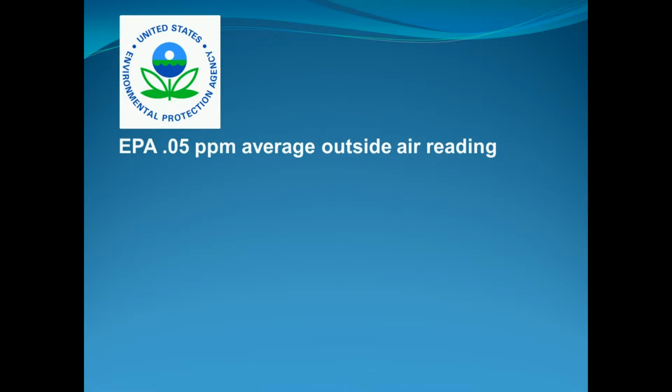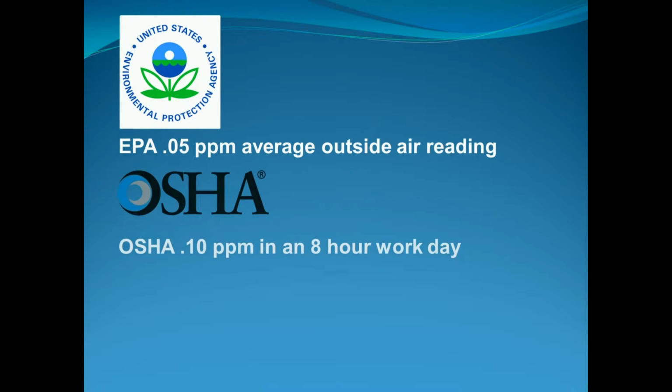So ozone is Mother Nature's way of oxidizing gases, but it's done in a specific amount outdoors. Outdoors has about 0.05 parts per million of ozone. Indoors, OSHA is a pretty strict organization. Any contractor that's listening now will tell you they're regulating our businesses. They say in an indoor environment you can have up to 0.10 parts per million, twice what's outside. Well, that's in an 8-hour workday. So a little bit of a higher level, but for a shorter period of time.